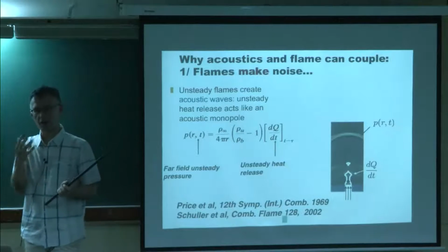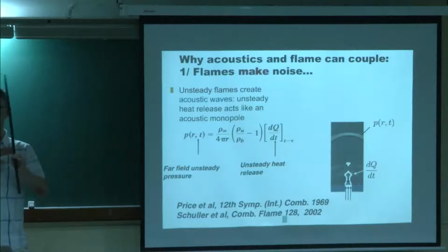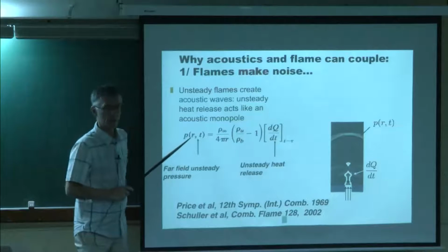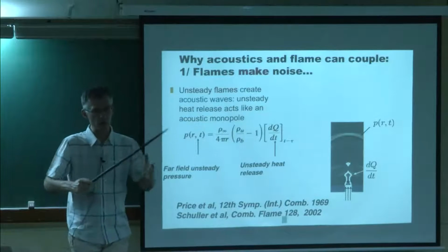By the way, this tells you something. If a flame is steady, it makes no noise. Even if it's a big flame, if it doesn't move, it won't make noise. Now, if it is unsteady, it will make noise. So any flame which is unsteady will actually produce noise.